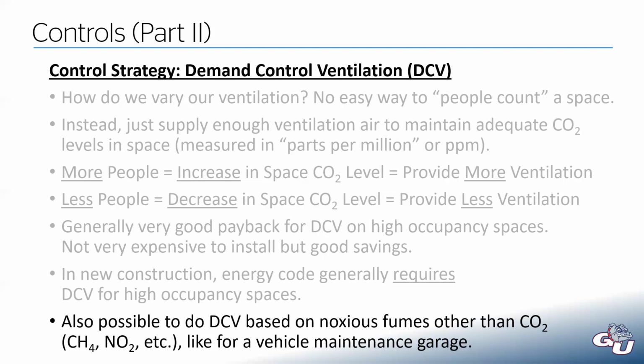So when we talked about the Spokane Transit Authority maintenance garage, I briefly talked about this, where we installed carbon monoxide and nitrogen dioxide sensors in the space that would increase and decrease the ventilation air based on those fumes, because those are the fumes that vehicles emit. So it's not always about CO2, although it usually is, or at least that's the most common application.